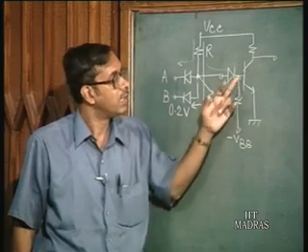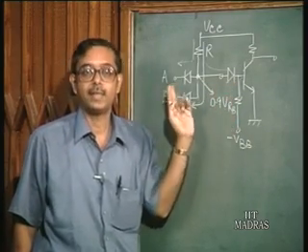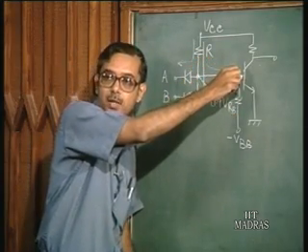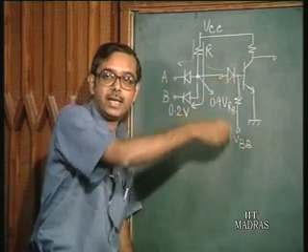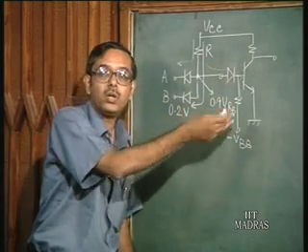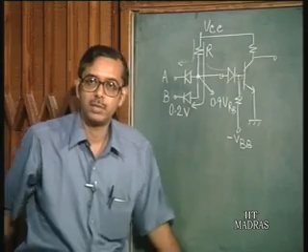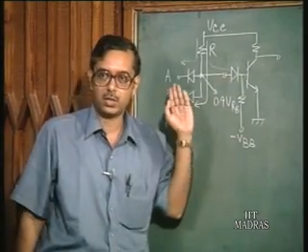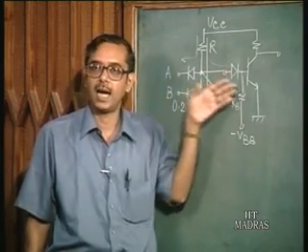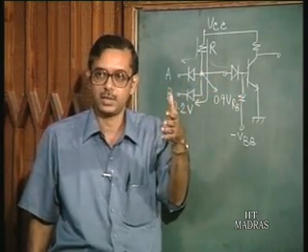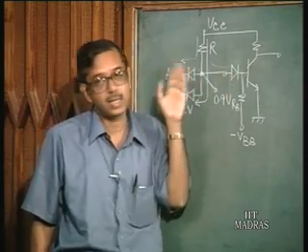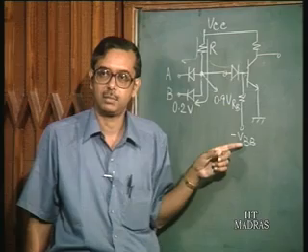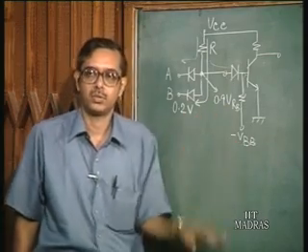Number two, if you put a resistance like this, when the transistor is switching on, the current has to flow into the base, and a part of that current actually gets diverted here. So the entire current does not flow into the base, and so it slows the device. You know that in order to switch on the transistor, you require a sufficiently large base current flowing into the base of the transistor, as we have already seen with the on time of a transistor, but this is going to divert some current. So this is not a good solution.